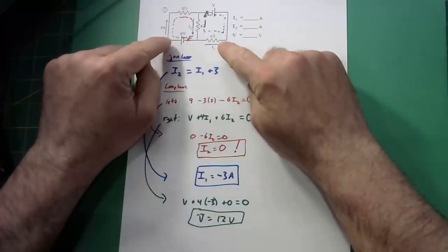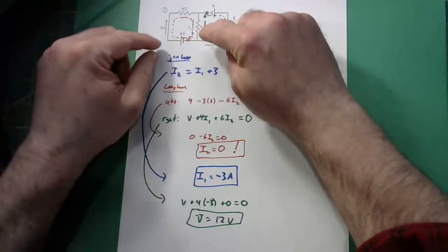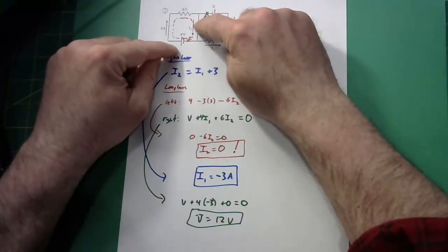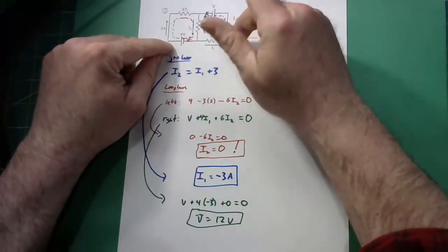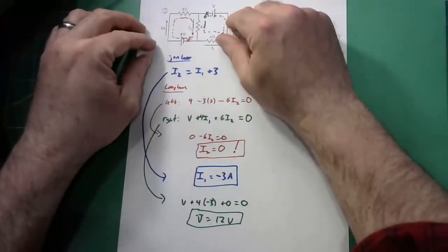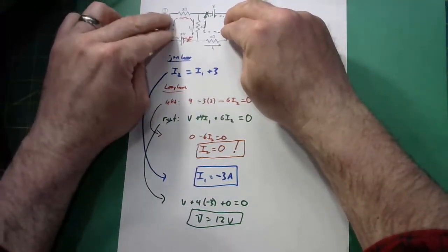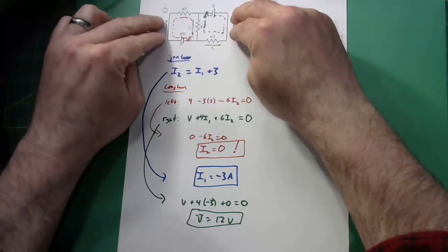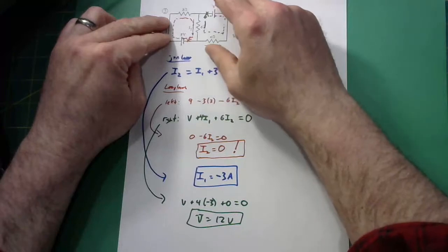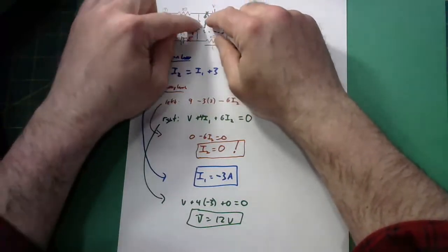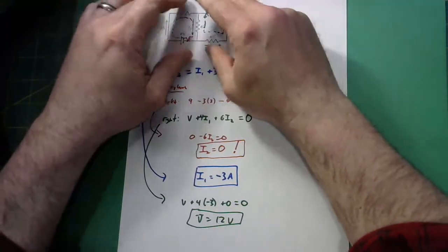We design devices that will work like this. We call circuits like this bridge circuits, where I'll have some path here, and maybe on one side I'll have an adjustable resistor, or I can do things with adjustable capacitors too, but adjustable resistor. And maybe over here there'll be something that I'm trying to find the resistance of. And so I can adjust the resistance here to change the amount of current flowing, the voltage, and everything, so that the current going through here goes to 0.